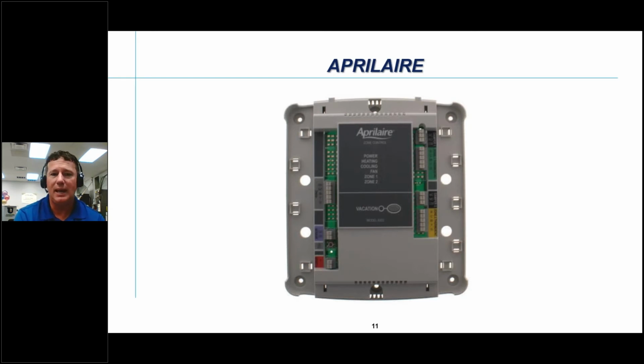So when we talk about that communicating platform, they all have their own specific communicating zone controls, where the traditional zone controls that are operating on legacy wiring through any of these brands is not going to function. And then we have Daikin out there that doesn't even have their own zone control. We're going to talk about that in a minute, though. And then finally, we have Amana moving away from that ComfortNet communicating system, going back into a legacy controlled thermostat.